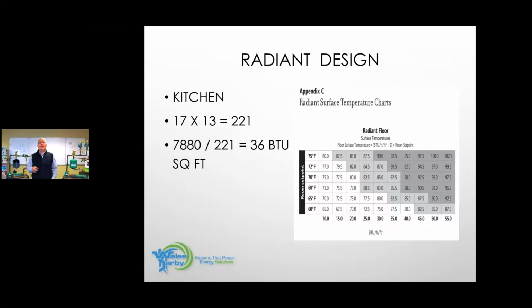So how do I figure out how much tubing, what's my supply water temperature, and what size circulator? And what's my method of attachment? You've got up to 7 different choices. So we're going to go from underneath the floor. It's a very common install, and we're going to use what's called joist track plates.